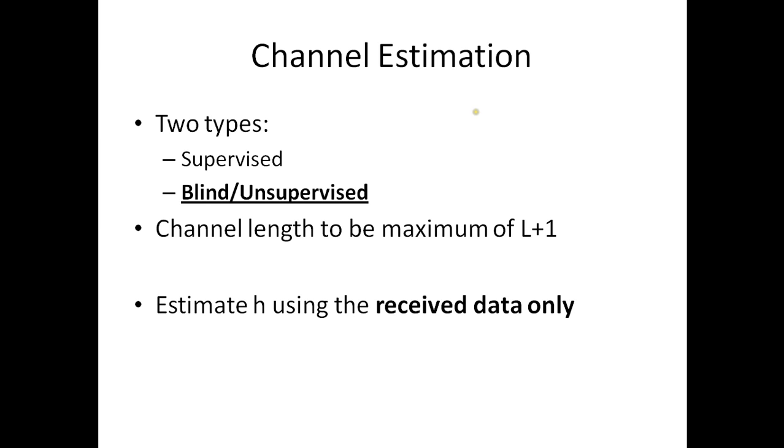Now coming to channel estimation. Channel estimation is particularly important because the knowledge of the channel will affect the link budget analysis in a major way, because the entire link budget analysis will assume certain characteristics of the channel and then perform. So the entire economics of telecommunication is dependent on how good the estimate of the channel is.